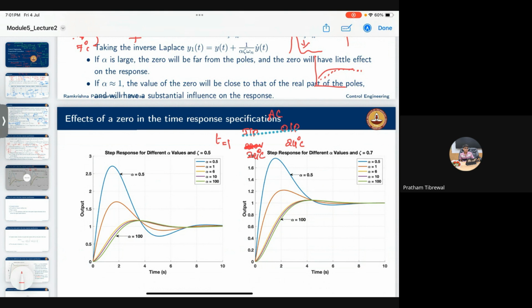After 2-3 minutes, it will reach 24 degrees Celsius. But because of some external disturbances, after 5 minutes, it goes to 26 degrees Celsius. My sensor is reading it as 26, but my set value is 24. So this is the difference, 2 degrees Celsius.